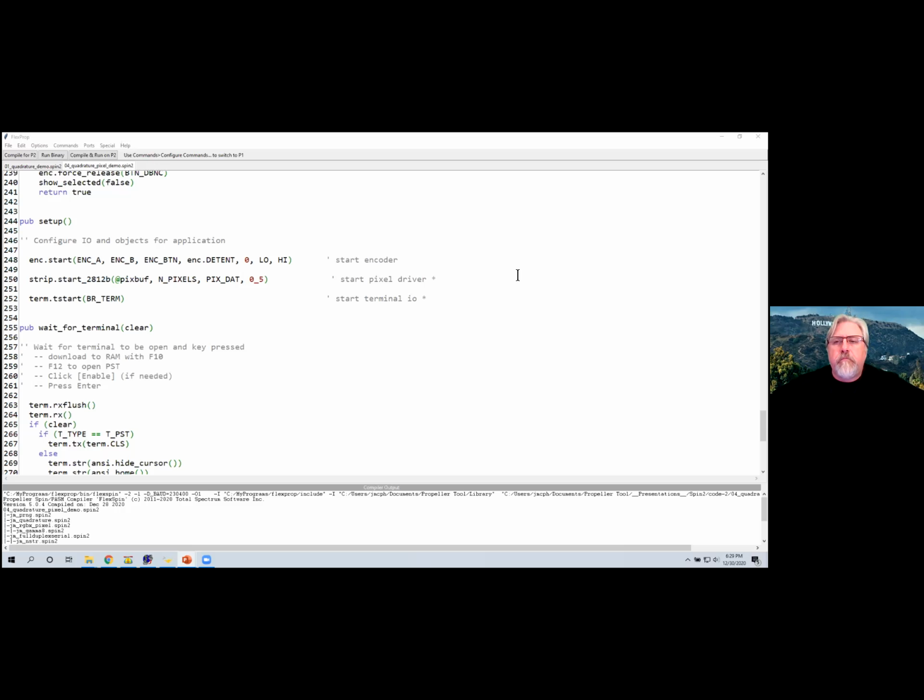Now, one of the problems is most of the magnetic tapes that you can buy, the way they come off the machine, the pattern is the wrong direction. So you have to kind of search around to find something that has a wide enough pattern that'll give you whatever type of length that you're trying to shoot for. But it can also be used to put around maybe a shaft if it's large enough, and just glue that tape there so you get a real high resolution signal off of like a shaft of a motor or some other spinning object.